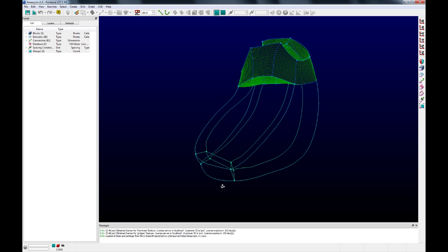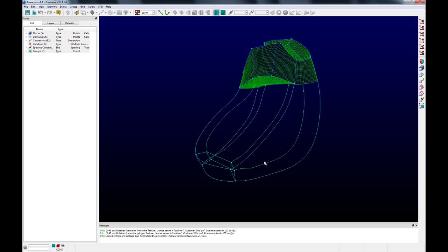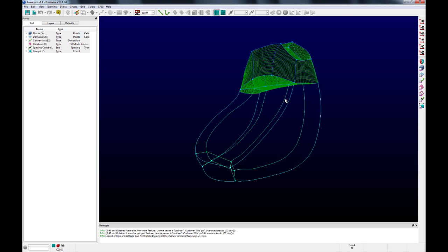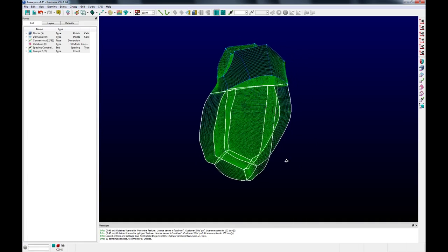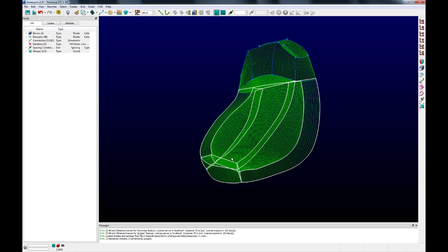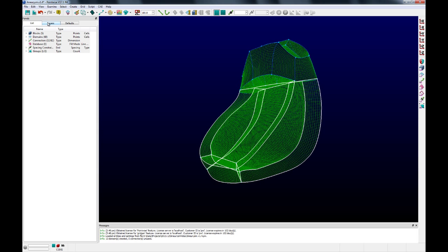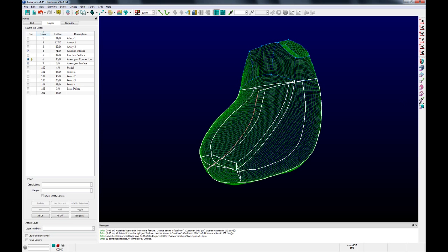And so now this has all of the internal structure, and all that's really lacking is the internal domains and everything. So I'm going to go ahead and select those. Again, I've grouped the connectors for convenience. We'll go up here, go Assemble Domains, and you can see that the topology is going to be created. So we have a nice internal structure ready to go. We'll go ahead and turn on the surface.